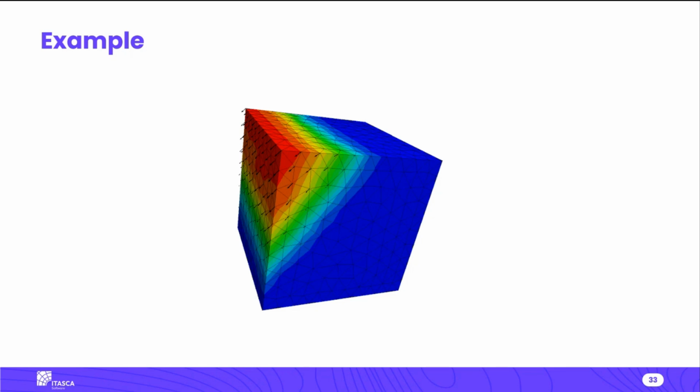Imagine we were trying to simulate a bench and we wanted to see whether it's going to fail or not based on certain different rock material properties. So this has no joints in it. This section is all about zones and zone constitutive models. We can do that in 3DEC. We can make a purely continuum model, and that's what we're going to do right here.